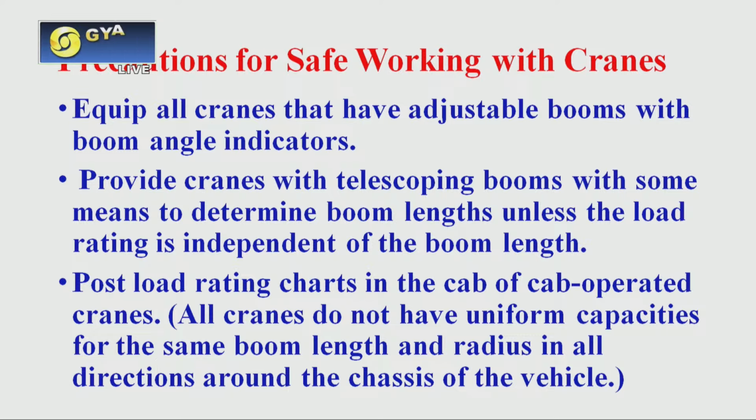Third, post load rating charts in the cab of cab-operated cranes. All cranes do not have uniform capacity for the same boom length and radius in all directions around the chassis of the vehicle, so for that purpose that chart should be there.